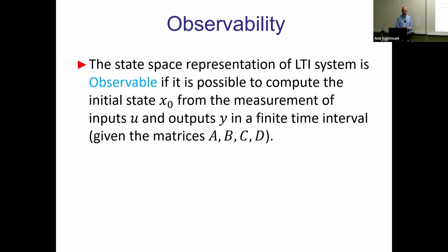Okay, an additional thing, which is called observability. Now I will describe the problem that we will eventually have, and we will work on it again. We'll have a special lecture on observability and designing observers, and getting later to Kalman filters, which are also observers. So here's the problem. You have your input u, you have your states x, then you multiply that x by matrix C, and then you get your y.